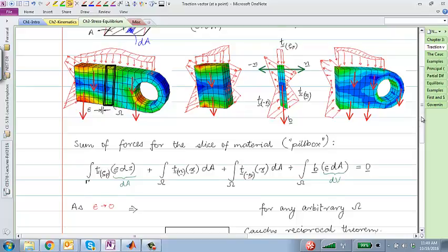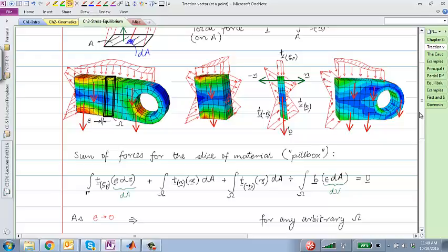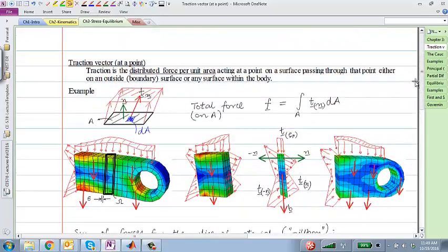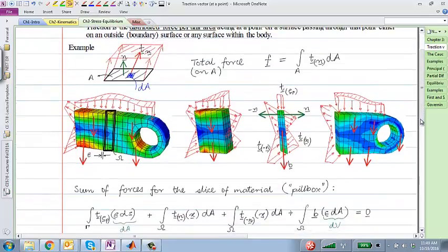So let me try to derive some relationships related to traction. But go ahead. Before that, when we define traction, do we assume that over that complete area A, whatever direction the traction has will be constant? No, we don't. This entire area could be some big area, right? So what we are assuming is that in the limit, on this small dA, there is some constant traction. So on different dAs, the traction could be pointing in different directions, but we sum them up just like any vector addition. Okay.